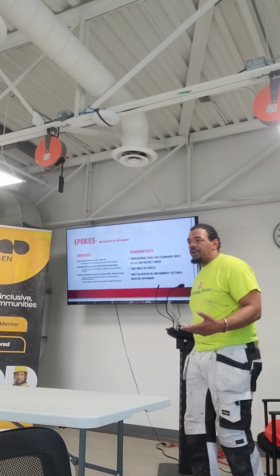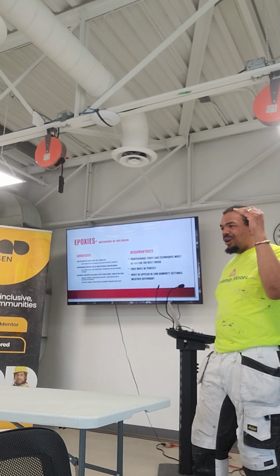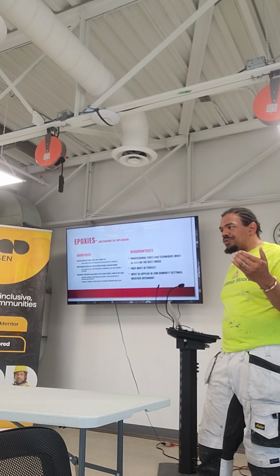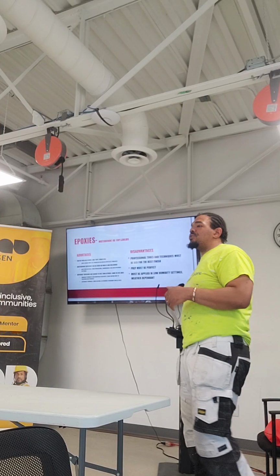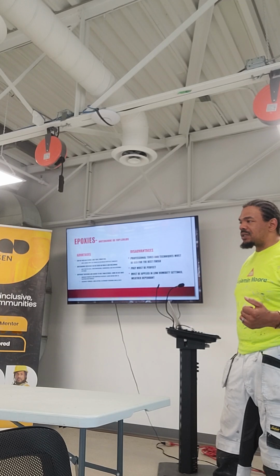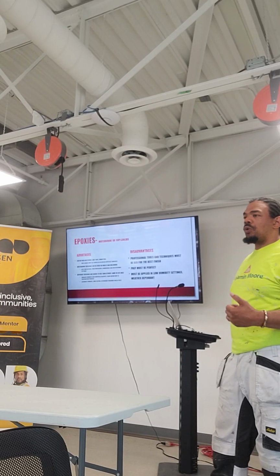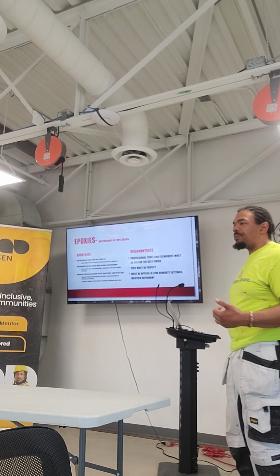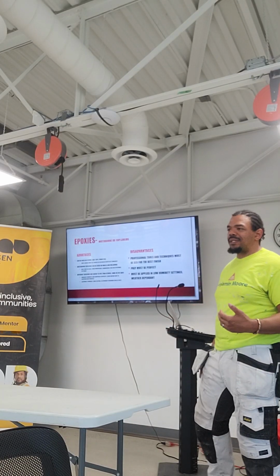So, epoxies. Now, this is the professional grade for all coatings. If you can install epoxy and have it work correctly, that's the mark of a true craftsperson. Epoxy flooring. Epoxies are also used in medical facilities because of their chemical resistance and their marring resistance. You can get an epoxy that's waterborne and use it on the floor. You can also get waterborne epoxies that can be rolled and brushed onto drywall and masonry. You don't really see many solvent epoxies, but what they are is 100% solids.